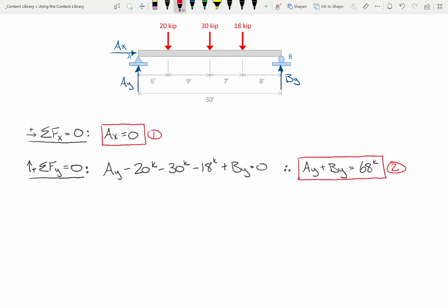So instead of our moments being defined as r cross F, I think we're going to be able to use this definition a lot more easily. Now remind me, how do we get the moment arm? It's the shortest distance from the line of action to the point in question. With me so far? So, let's be strategic about this. I can pick any point I want.